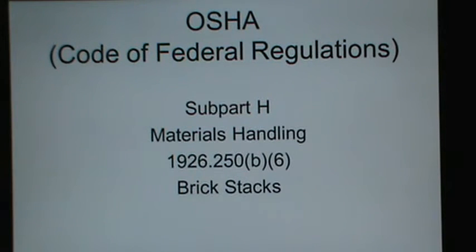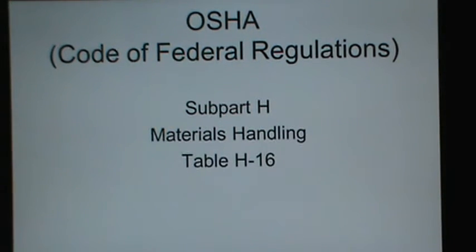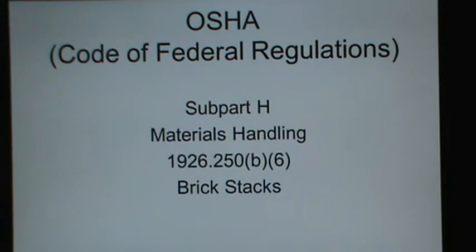Drop down about 4 paragraphs or so, and we're going to talk about stacking brick. Alright, brick stacks shall not be more than 7 feet in height. When a loose brick stack reaches a height of 4 feet, it shall be tapered back 2 inches in every foot of height above the 4-foot level. The next paragraph talks about stack and block, so make sure that you can find that. If a block is stacked higher than 6 feet, the stack shall be tapered back 1/2 block per tier above the 6-foot level. Make sure you can find that.